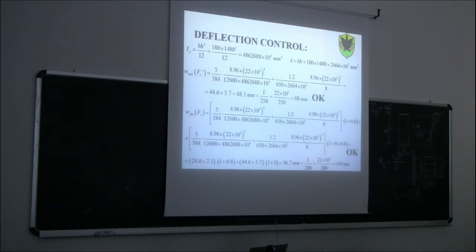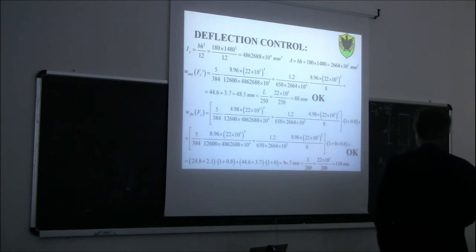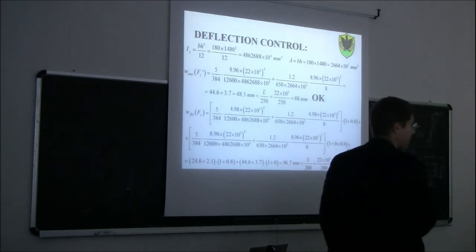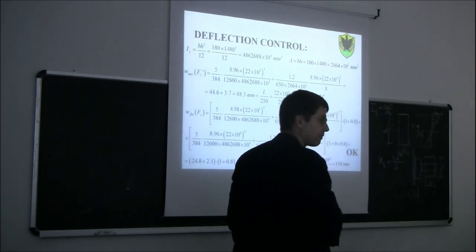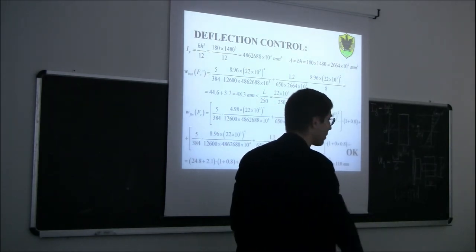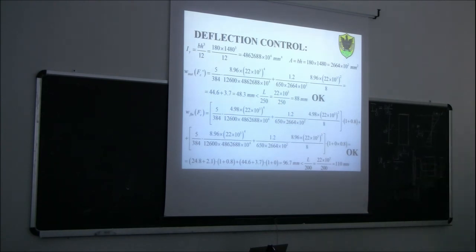As you can see here, the safety margin is much lower than before. Because in this case we have 97 against 110, so we are quite close anyway. So you can see that particularly the second, the final deflection, may easily be the governing design criterion.